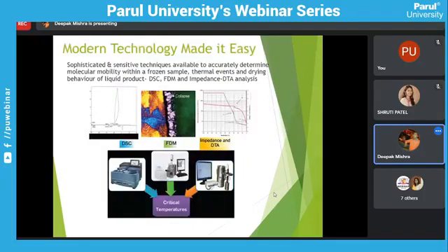So how do we select the cycle development in the lyophilization process? How to select means how to select the temperature, which temperature is suitable for any product. If I'm using a peptide, which temperature do I use for freezing, which for primary drying, and which for secondary drying? It is all dependent on the critical temperature. Critical temperature is determined by 3 or 4 techniques.